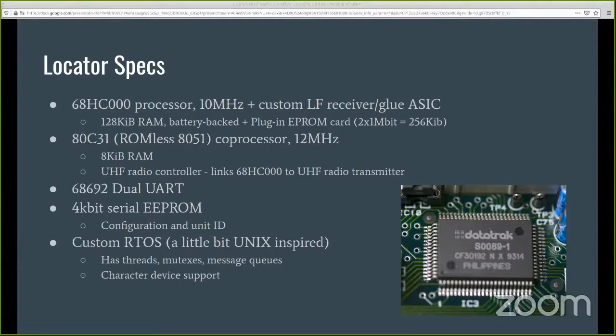It's perhaps a little bit OS-9-ish, a little bit over-engineered if I'm being brutal, but it gets the job done. It's time deterministic. Everything is locked off a 1 kilohertz, 1 millisecond tick, which comes from the radio receiver chip. So it gets periodic interrupts and everything is timed off that. That also synchronizes to the radio signal that comes in. It's a pretty unique piece of equipment.